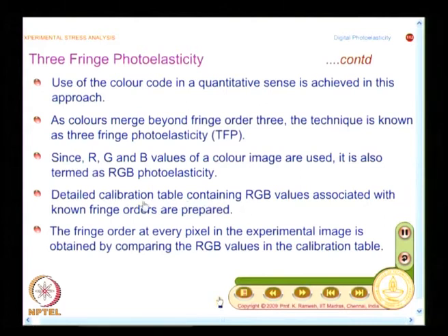Use that to prepare a calibration table. And you find out the fringe order in an unknown problem by comparing the RGB values with those in the calibration table.